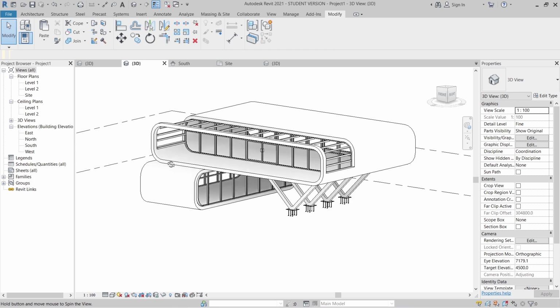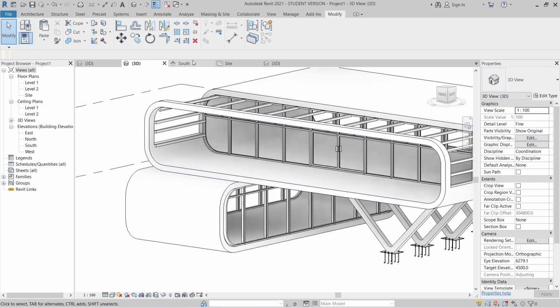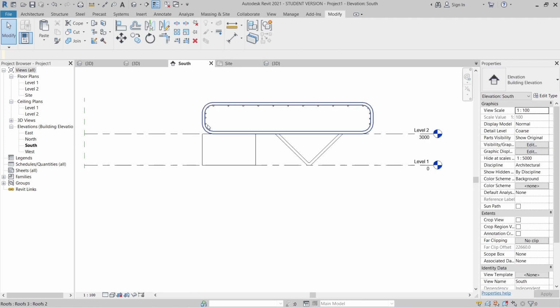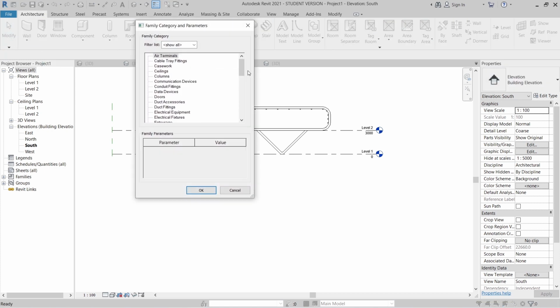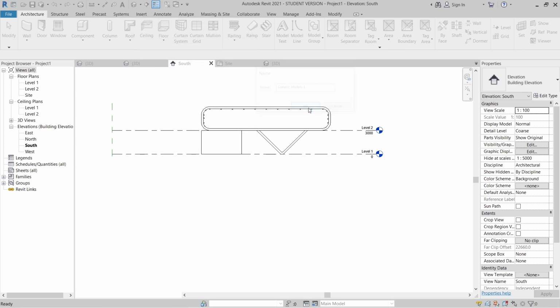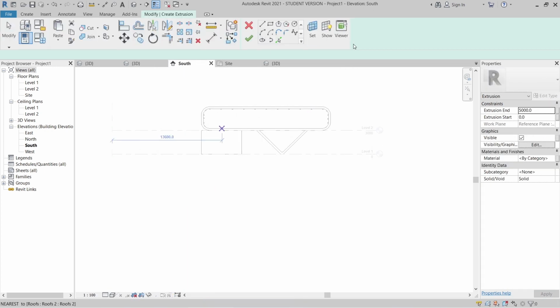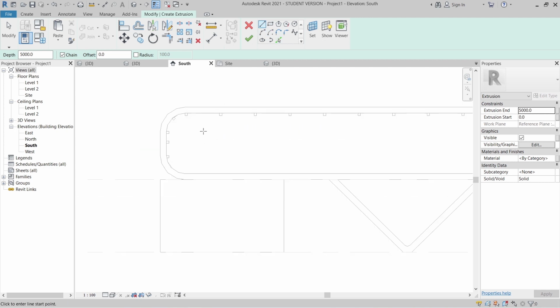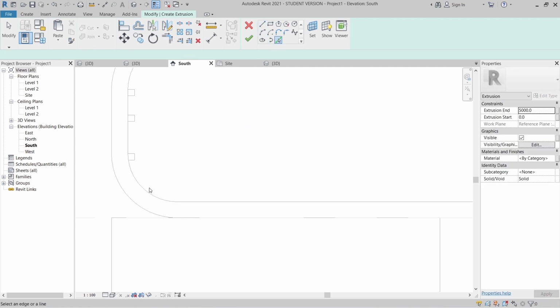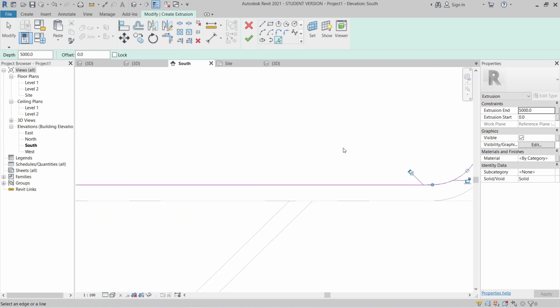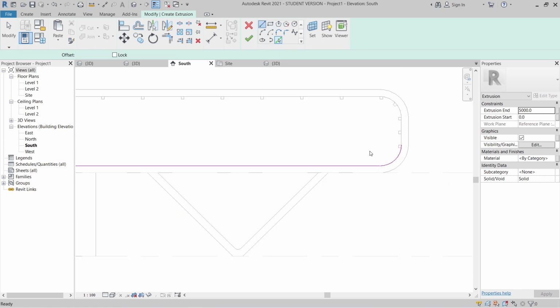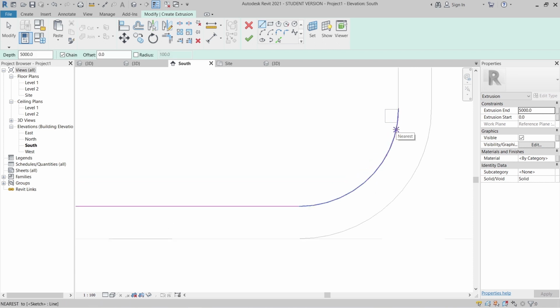Okay, now it's time to create our custom railing. Start from our south elevation again, and then go to our architecture tab, model in place. Using generate model is okay. It's okay again. Extrusion, and use our pick line. Going to pick here 1 and 2 and 3. Hit escape. Start connect from here. Start from here